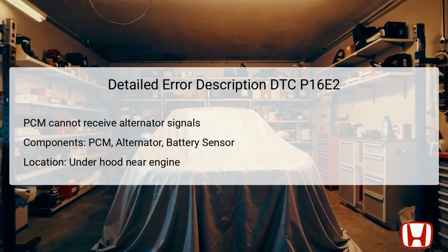The PCM is typically found mounted near the engine compartment and is responsible for diagnostics and overall vehicle control. The alternator, located similarly under the hood, functions to charge the battery and power electrical components. The 12-volt battery sensor, also attached to this communication line, helps monitor battery conditions. If any part of this communication line is faulty, it will trigger the DTC P16E2.